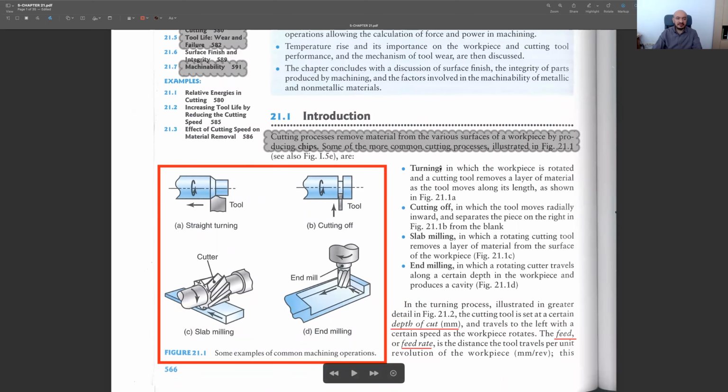And what we do in these machining operations, we need to use a tool. As you see here in all of these, we have cutting tools. This is an example of an insert, a kind of cutting tool. And with the help of these cutting tools, they have sharp edges, and we try to remove material, we generate some chips, little chips, sometimes continuous, discontinuous chips, we will talk about them. And once you remove material from the initial workpiece, you will be doing a machining operation.